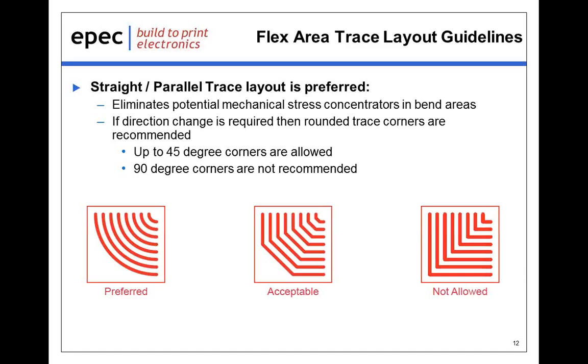Now, not all designs will allow for that, so if a change in direction is required, then we definitely recommend that the trace corners be configured in a rounded shape or configuration, if at all possible. Utilizing 45 degrees is allowed. Using 90 degrees is definitely not recommended.